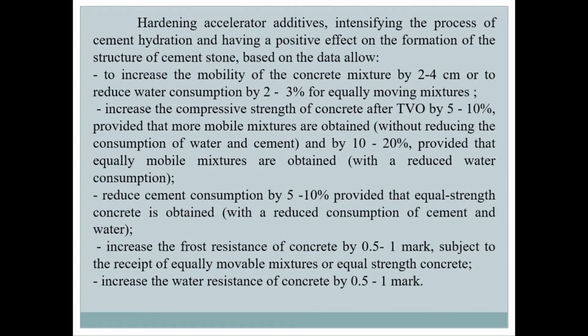Hardening accelerator additives intensify the process of cement hydration and have a positive effect on the formation of the structure of cement stone. They increase the mobility of the concrete mixture by 2-4 cm or reduce water consumption by 2-3% for equally mobile mixtures.